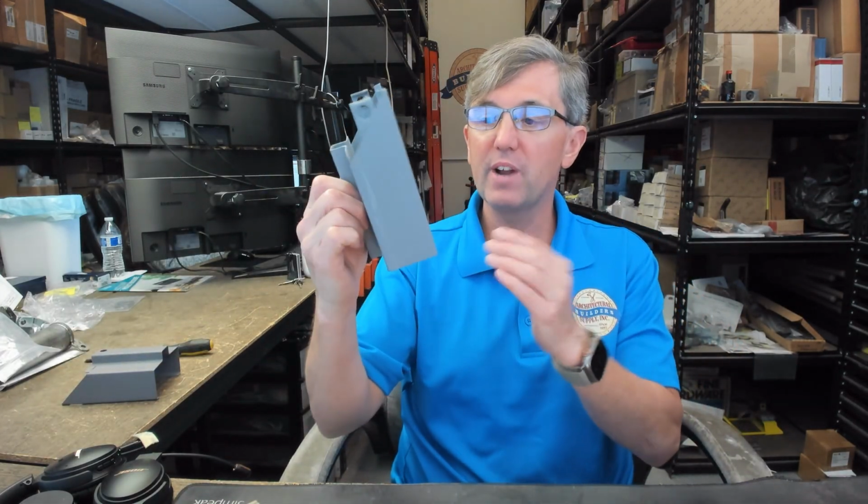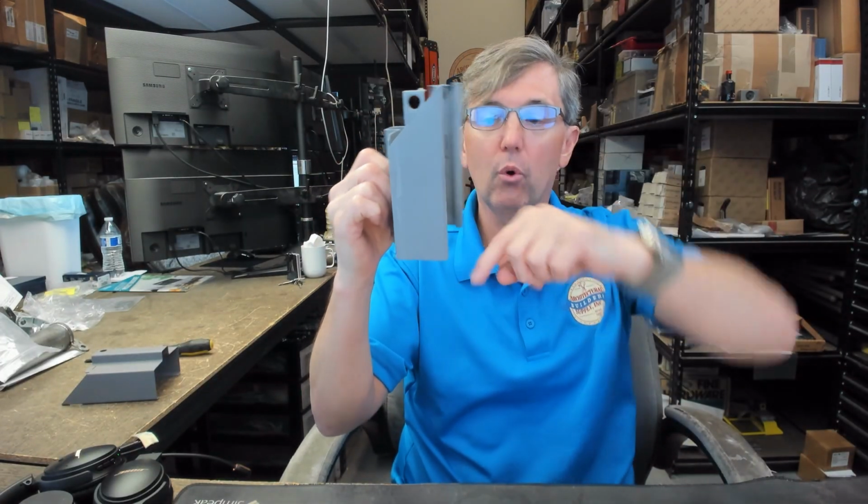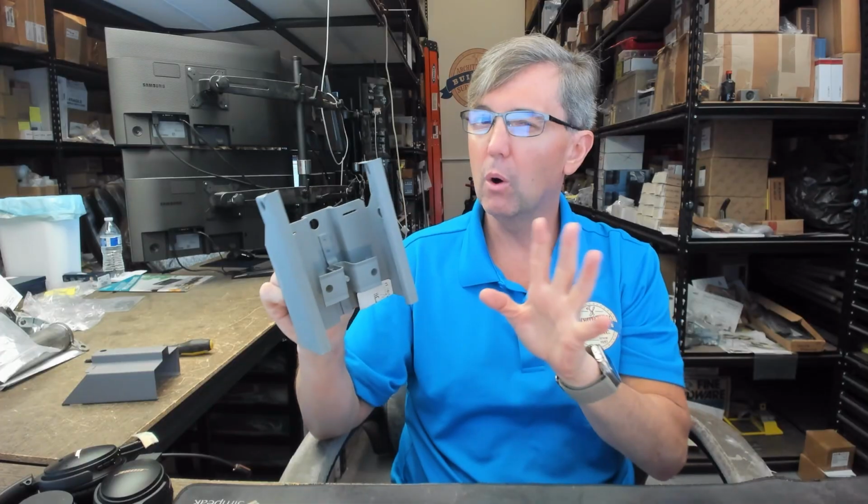So you can have a back bend return on a masonry frame, and I think in those applications where you're doing interior work, the frames are going to be on site before any framing is done. Yeah, back bend returns with the right type of anchor would be a really good idea. Another facet of drywall frames is that they don't have floor anchors. I had mentioned earlier about the dimples. You're not going to have a welded in angle plate that you'll shoot down to the floor, just those dimples.